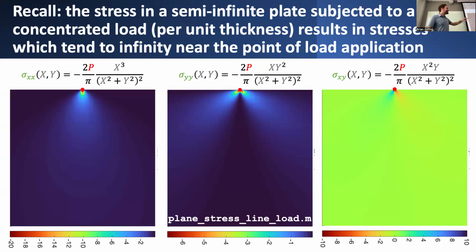In any case, we saw that the stress in each one of these different components of stress will zoom off to infinity at the point of application of the load. And if we look at what happens at increasing levels of distance from this load, clearly that concentrated stress starts to spread out and get distributed throughout the plate until, far enough away from that point of application of the load, it almost looks like nothing's happening. But sort of an interesting scenario.